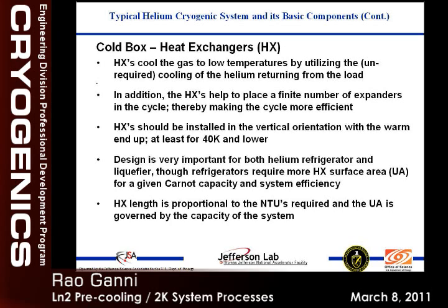Basically, as I said, it is a trade-off: each corner step improves it, but it costs you a lot more. So we balance with some heat exchanger in between. But we have to make this heat exchanger very effective so that the cost on your next corner step is not that high. So those are the things these heat exchangers do in between, and we have to be very careful how these are designed.